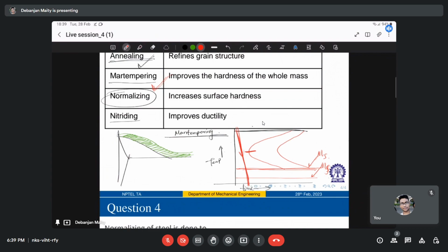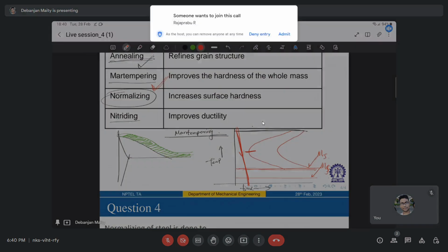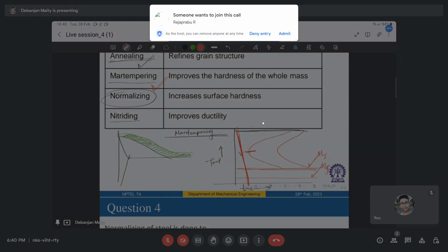So the main objective of tempering is to minimize this distortion and to eliminate the crack tendency from the higher cooling rate during the hardening process, right? And it should be noted that tempering cannot prevent these volume changes, which are inevitable in any kind of hardening treatment. With hardening there will always be some kind of volume change, which is inevitable; you cannot prevent this.